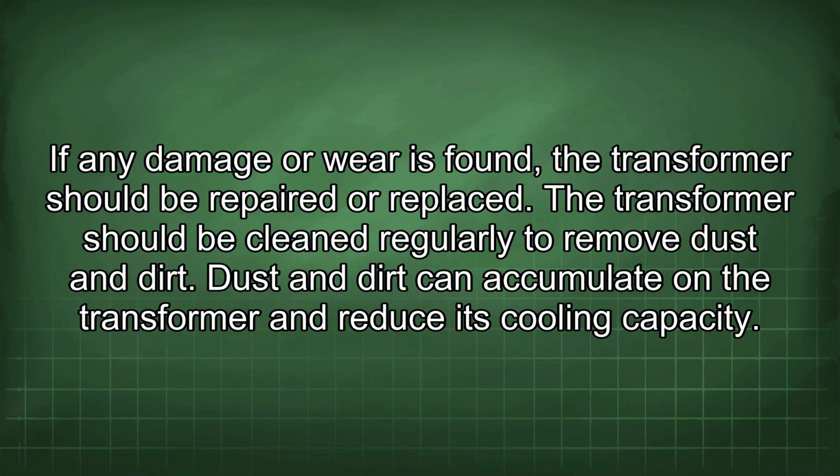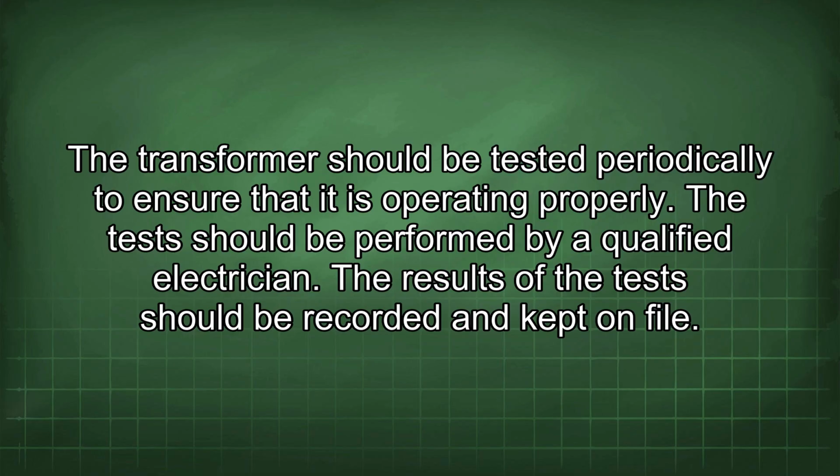The transformer should be cleaned regularly to remove dust and dirt. Dust and dirt can accumulate on the transformer and reduce its cooling capacity. The transformer should be tested periodically to ensure that it is operating properly. The test should be performed by a qualified electrician. The results of the test should be recorded and kept on file.